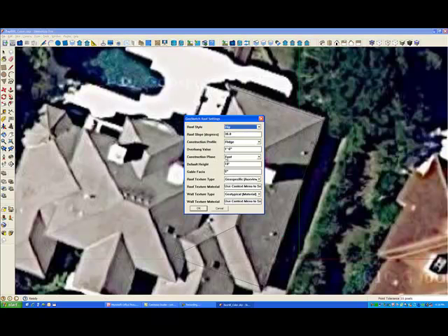And then we'll change our parameters such that we're building the main part of the house, which is a two-story building. And we'll again digitize the ridge line of that hip roof. And our inferencing will tell us when it's perpendicular to the previous section that we made. And then we'll switch to doing ridge-ridge for our geometry.